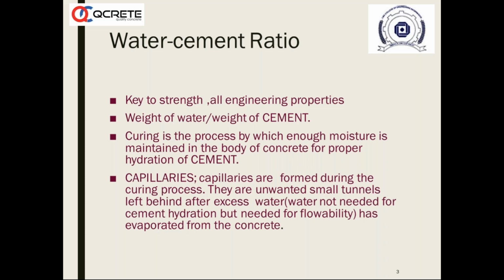Again, coming back to our subject of water cement ratio, the cement hydration, that is the reaction between water and cement, can take place if there is a certain amount of water in the body of concrete. Scientists have found long back that you require about 0.22 to 0.27 as the water cement ratio.